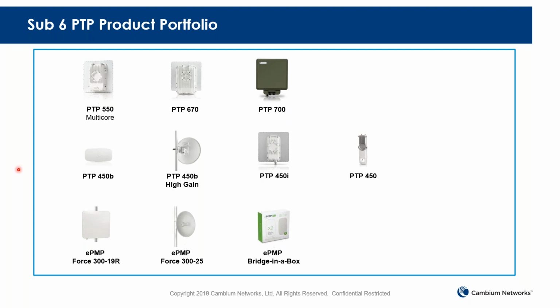Actually, if people own a block of spectrum, then using the high gain antenna, they can maximize their frequency reuse. If you're using a standard antenna, because it cannot get rid of certain interference on the side lobe, their frequency reuse is not as great as with a high performance antenna. There's no antenna gain difference, but because of this slope thing, there is a big cost difference. So it's really about where you deploy this, and do you really need it.